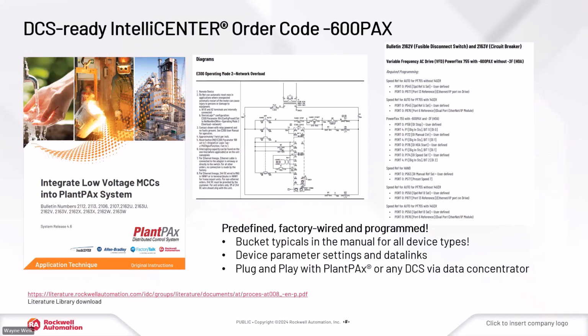So this is another thing that not a lot of people know about. The IntelliCenter system has the ability to create up front what we call a DCS ready interface, and that can work with a PlantPAx DCS, that's Rockwell, or it can also connect to a third-party existing DCS if the customer is unable to use the PlantPAx when upgrading the MCC.